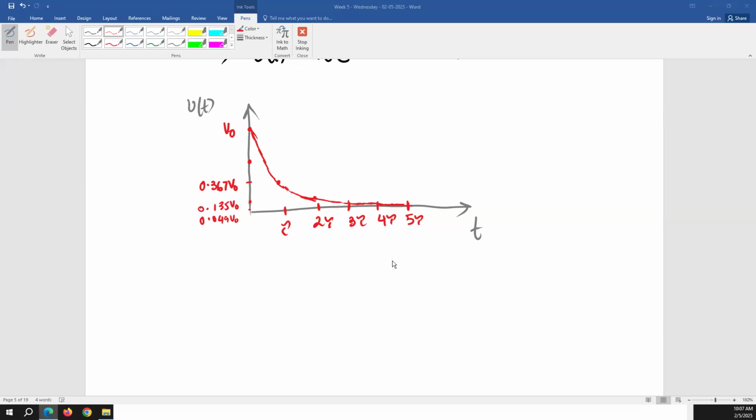If the capacitor is charging, we're going to discuss that when the source is there and the capacitor is charging, before it starts discharging. If the capacitor is charging, again, we assume that in around 4 to 5 time constants, it is fully charged and will have the maximum voltage across it. Because after that, mathematically, it's going to take infinity to charge and discharge, but practically it is just 4 to 5 time constants. The value is low enough that we can ignore the rest of the values.